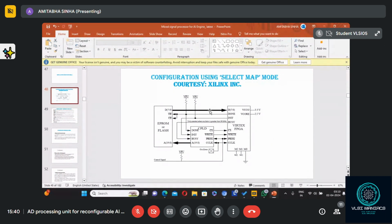The same data bus can be connected to the data bus of the next FPGAs and so on. In that way, using one CPLD and the same EEPROM, a number of FPGAs can be programmed simultaneously.